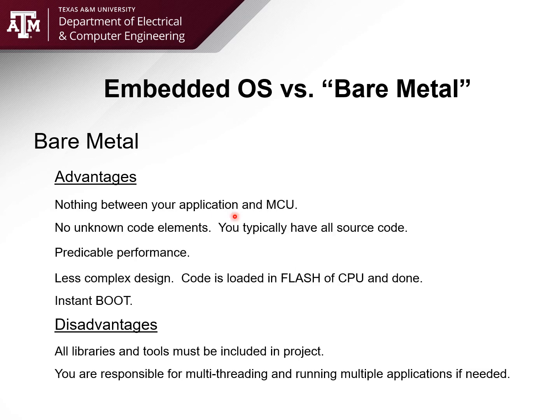Bare metal, there is nothing between you and the application. That's a big advantage. You know exactly what's going on, just like in the case I just gave. There's no unknown code. Everything is under your control. You have complete source code control. You have very predictable performance because of that. It's usually a less complicated design. It's usually a one-chip solution, or at least a one or two chip solution. And it's an instant boot.